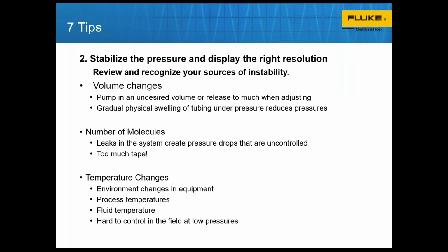Let's talk about stabilizing your pressure. This is one of the biggest complaints that people have. They'll pressurize a system and then the pressure will either wander up or drift down, and they just can't seem to get it stable or get it to maintain. So let's talk about a few of those different factors, and it comes back to that conversation earlier about volume and temperature and how they all interact with pressure.